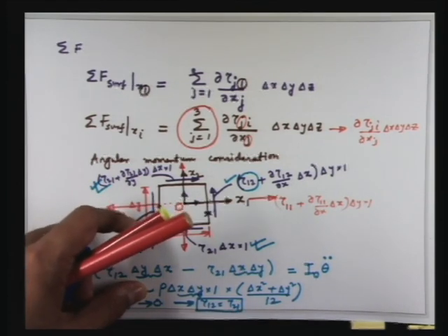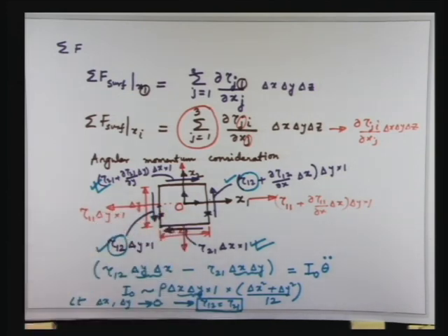Okay. So see, we have derived this equation based on two important considerations which I want to remark. The first consideration is straightforward, that we have considered the possibility of having an angular acceleration of the fluid element. So it is not necessary that for tau ij equal to tau ji to work, the fluid element has to be non-rotating or non-accelerating. It may be rotating but non-accelerating. Even if it is accelerating, the acceleration term goes away because of the higher order terms. This is the first thing. But this is not that subtle.